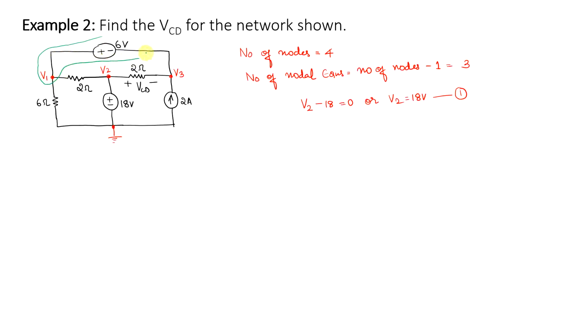When I mark the boundary, I need to be very careful to include both the two active nodes which were responsible for creating that supernode. Be sure not to include V2, because that is not part of it. Only V1 and V3 were responsible for creating this supernode.